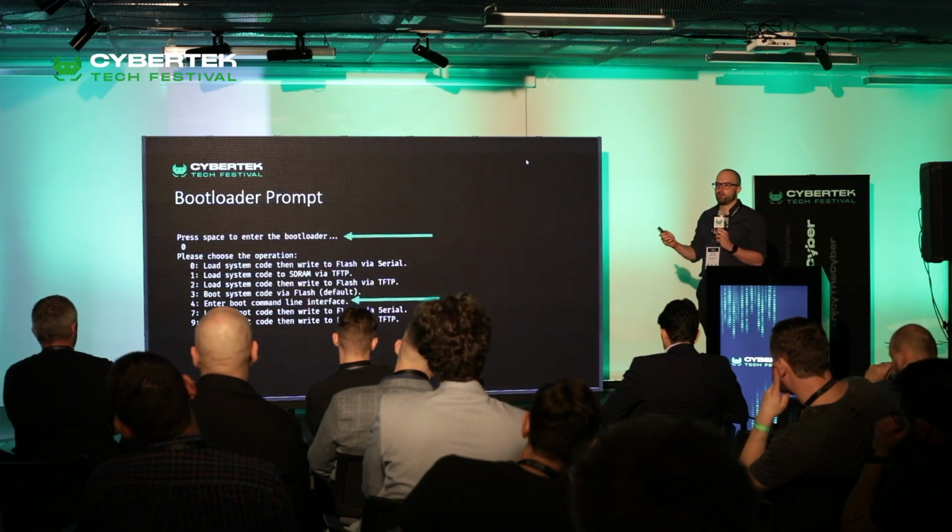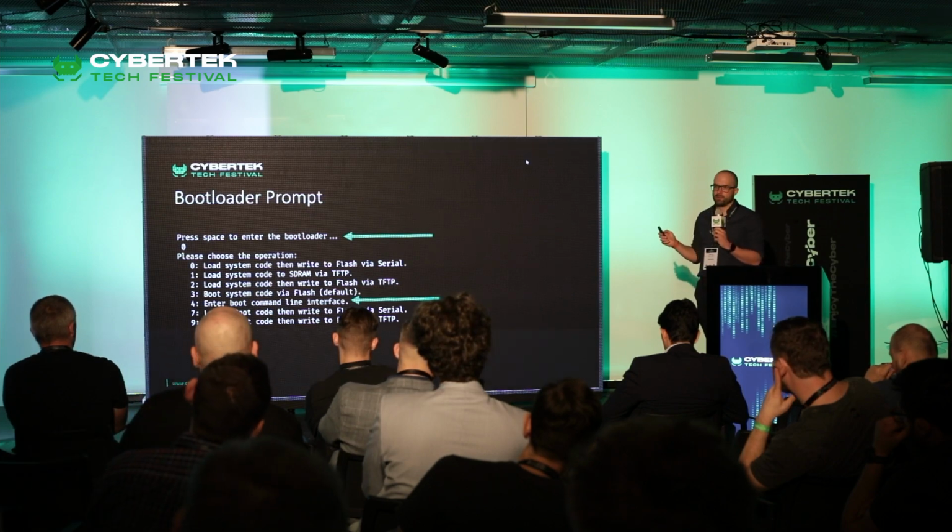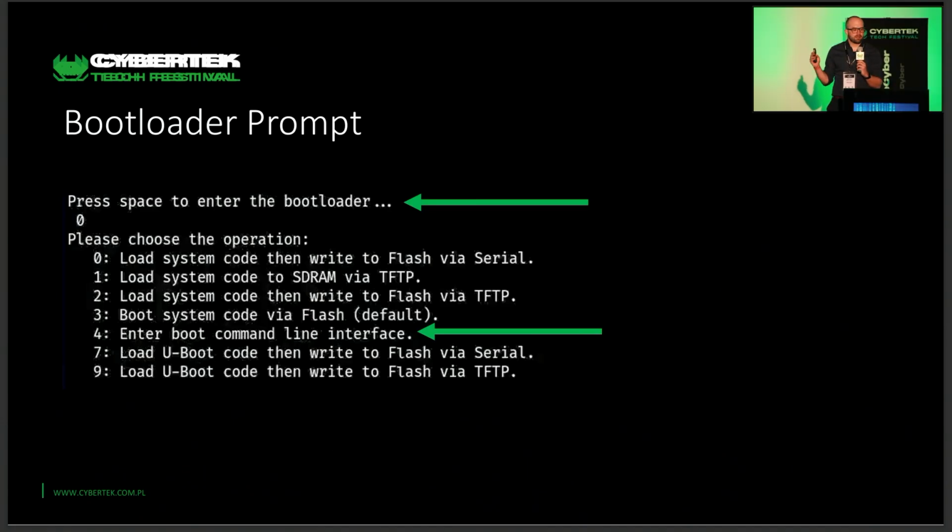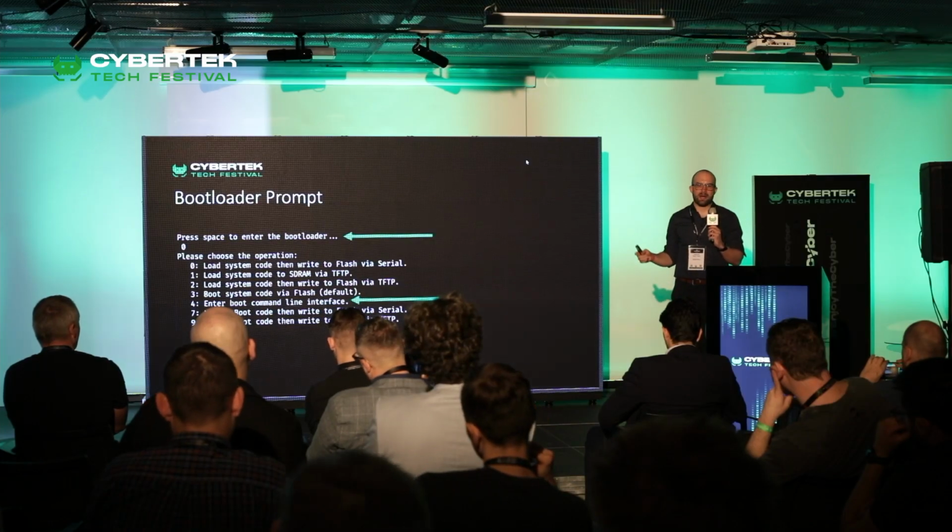If we scroll further up, we're also prompted for a spacebar press to enter the bootloader. But on this device, the timing window is so narrow that it's almost impossible to hit. Right? I was sitting like a maniac over the keyboard and slamming the spacebar, only to see that if I hit the timing window right, I'm presented with a second option to press number 4 to enter the command line interface.